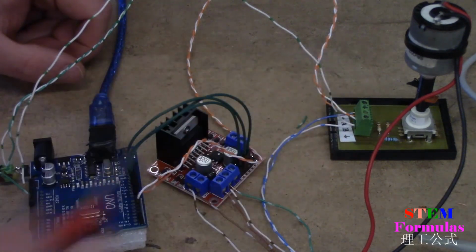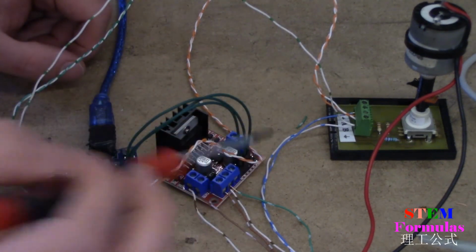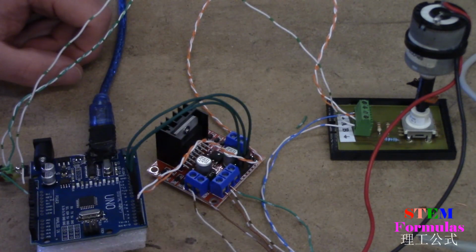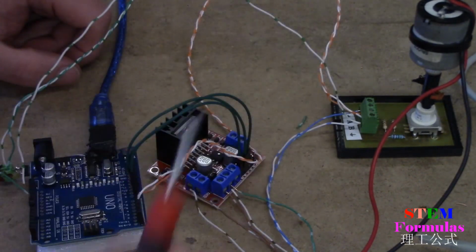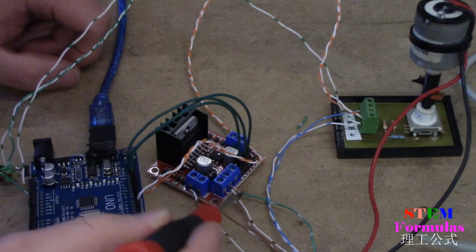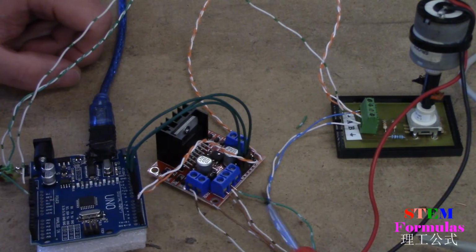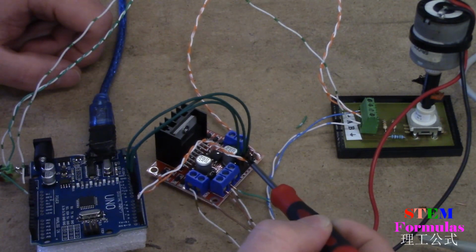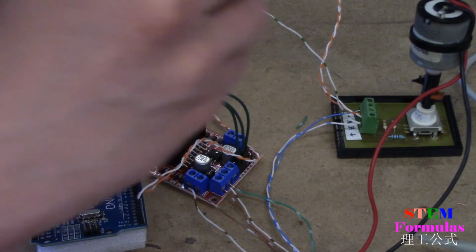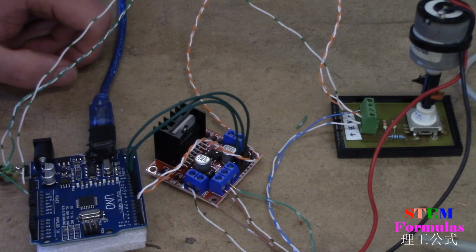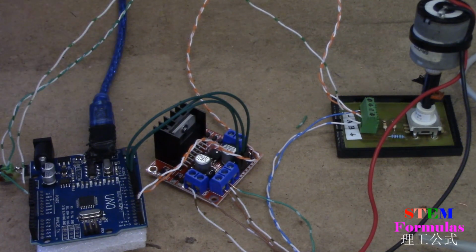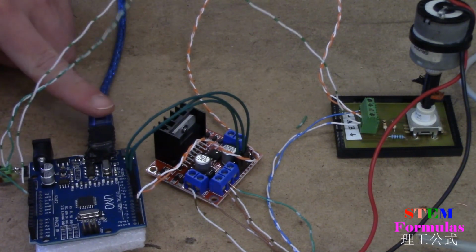So that's how you're connecting the grounds together. Next, we have the motor outs here, connecting to both ends of your motor. And you also have your in 1, in 2, and enable A, all connected in order there to pins 5, 6, and 7. And lastly, this here, you'll connect it to your computer.